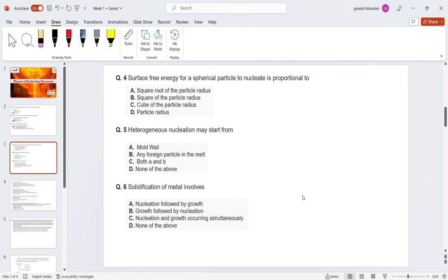In the soldering process, if your surface tension is more, which you can calculate from the Young-Dupré equation, just go through the Young-Dupré equation once after this session ends. What you will see is that if your surface tension becomes higher, then whenever you try to solder two elements, it won't solder those elements but will instead make some ball type of things because the surface tension is higher.